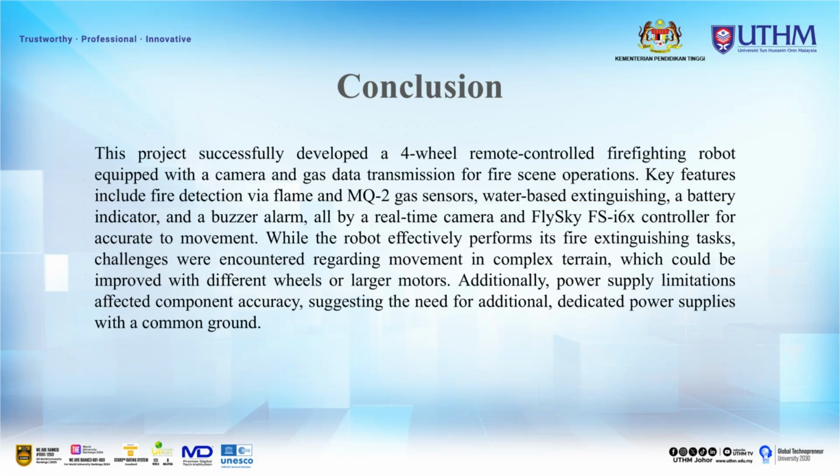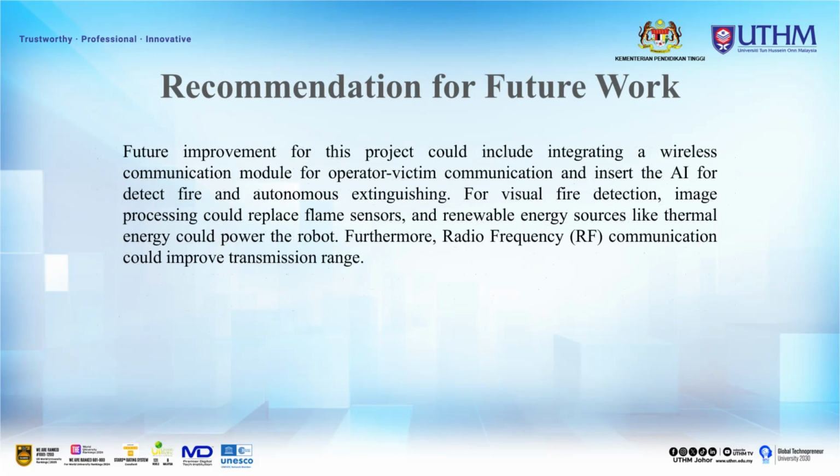Finally, this project successfully developed a four-wheel remote control firefighting robot equipped with a camera and gas data transmission for fire scene operations. For future improvement, this project can integrate a wireless communication module for long-distance communication and add AI for fire detection and autonomous extinguishing. For visual fire detection, image processing can replace the flame sensor, and a renewable energy source like thermal energy can power the robot. Also, radio frequency communication can improve the transmission range.